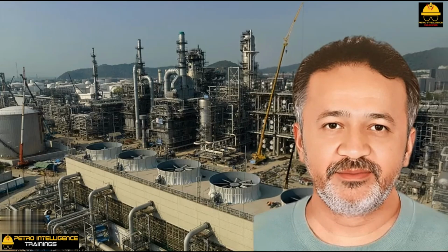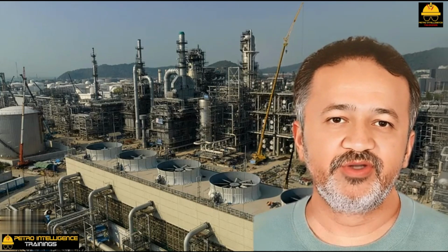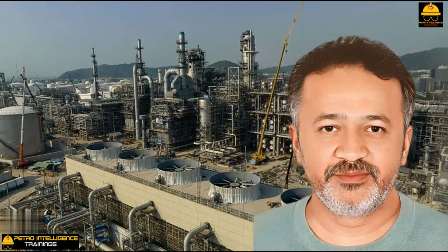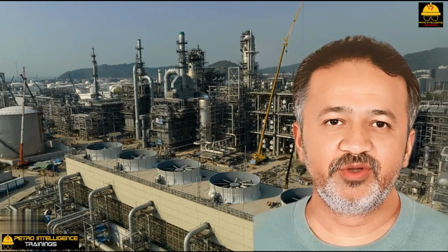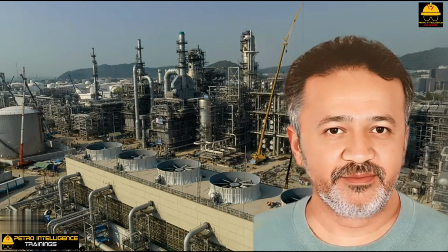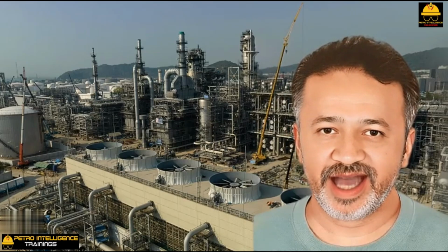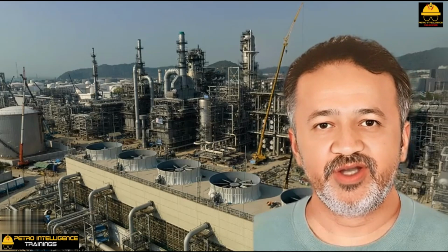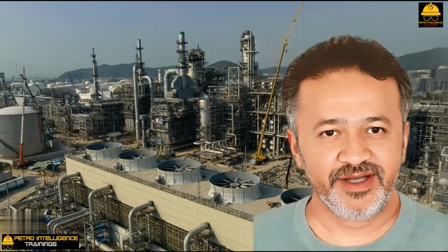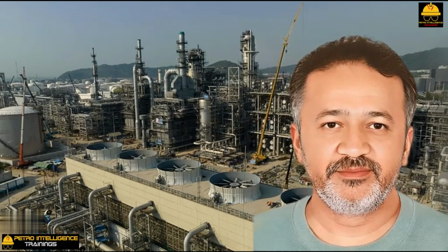Fin fouling. In a forced draft air cooler, cool air is blown through the underside of the fin tube bundle. In an induced draft air cooler, cool air is drawn through the underside of the fin tubes. Either way, road dust, dead moths, catalyst fines, and greasy dirt accumulate along the lower row of tubes.